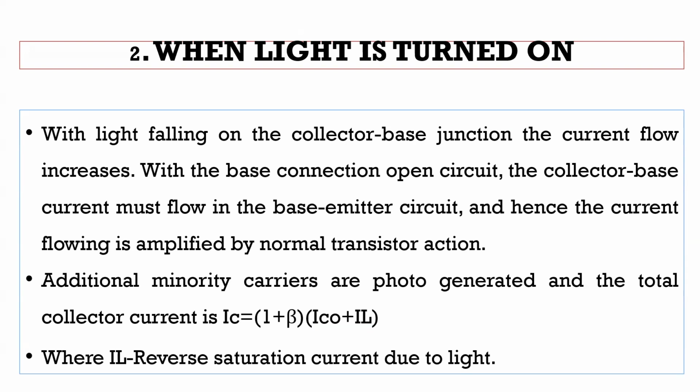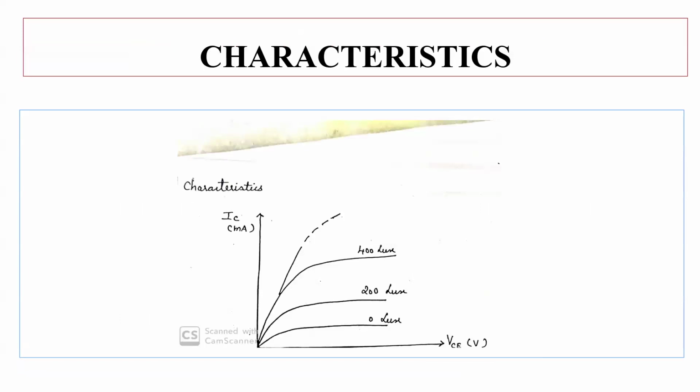The phototransistor is 50 to 100 times more sensitive than a photodiode, with a lower level of noise, and it has a high current gain. So how does it work based on these characteristics? It activates once the light strikes the base terminal and the light triggers it. The current slightly starts to increase. And what happens when the current increases? Then it is concentrated as well as changed to voltage. Generally, a transistor includes a base connection, but here the base terminal is disconnected, as the light is used to allow the flow of current throughout the phototransistor. It can be used with both BJT type and FET type. What we have discussed is the BJT type.